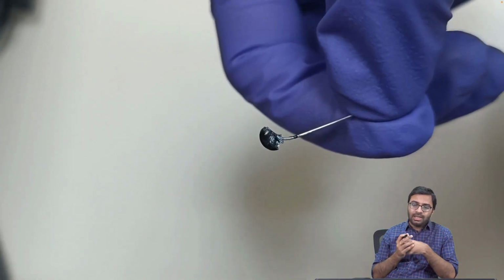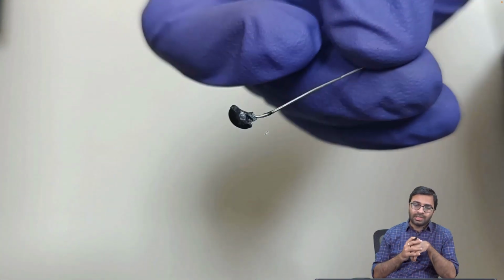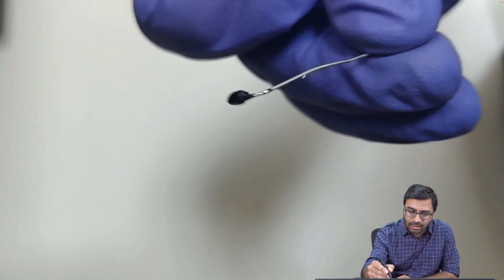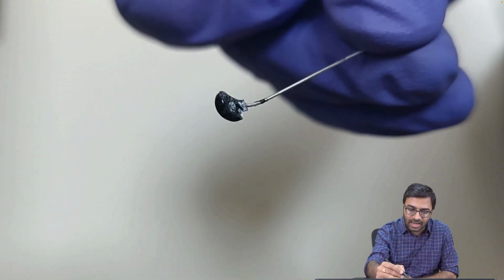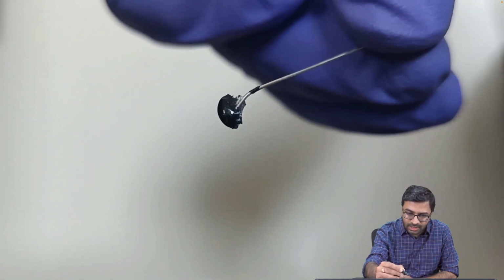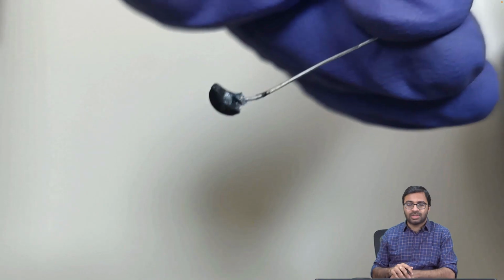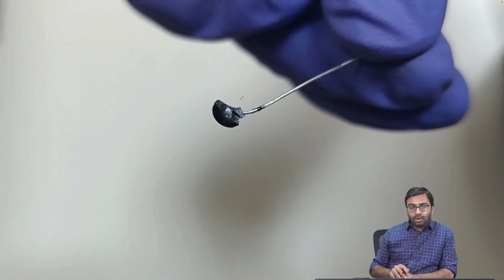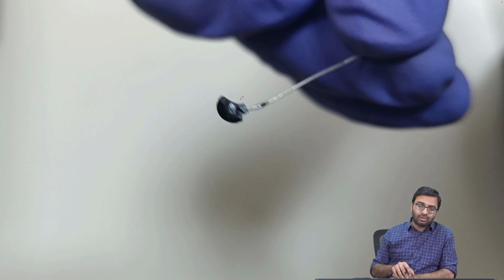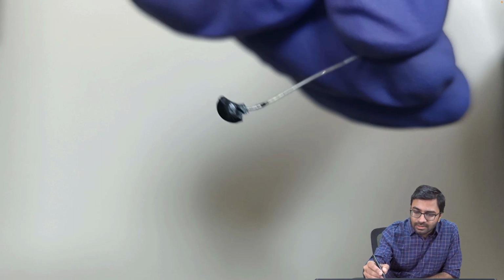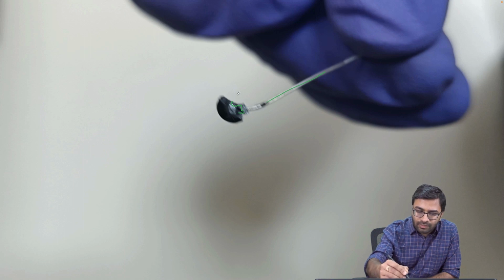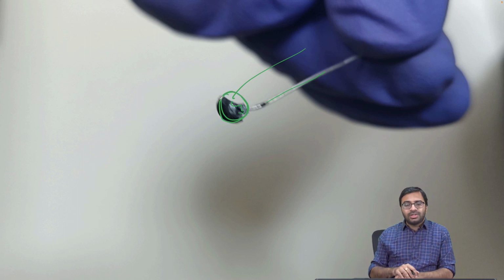And just to give you a better idea, I've crushed this sensor. Now in the video you can see that this metal terminal is connected to the active material. In this case, the active material is inside. The shiny material that you see inside is the active material. Usually these thermistors are made of metal oxides like nickel, manganese, and so on. And then this metal terminal is connected to this active material, and there are two different terminals likewise, and then they package it with a certain sort of encapsulation, right?